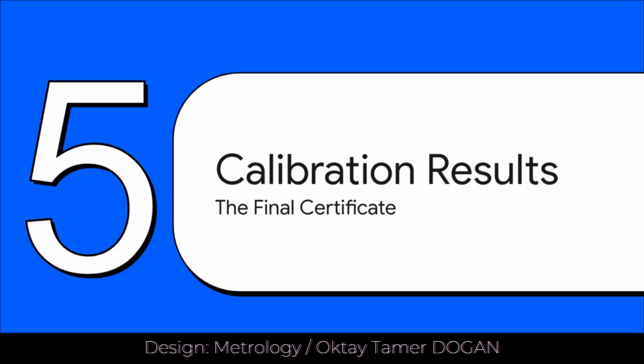And finally, Section 5, the final calibration result. When you actually receive a formal DKD R 5.7 certificate, you won't just see a single temperature telling you your chamber is good to go. You will see distinct, meticulously documented values. You get the controller adjustment, which is the basic difference between what your chamber's display says and what the reference standard actually says, right alongside the calculated spatial inhomogeneity. This tells you exactly how much variance you're dealing with across your entire useful volume.